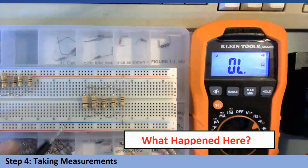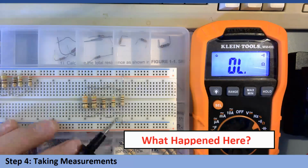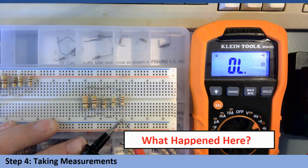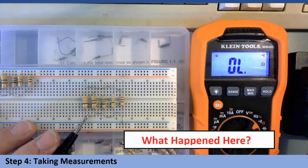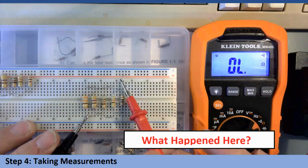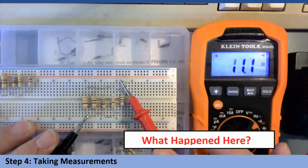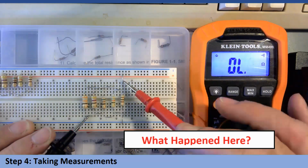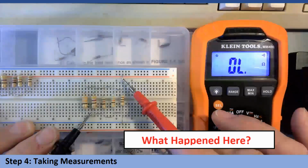I need to go from the start of my circuit to the end of my circuit. Since these are all in parallel, there is not really a start and finish. I'm going to go from here to here and see what I get. Now I'm getting a signal of continuity.